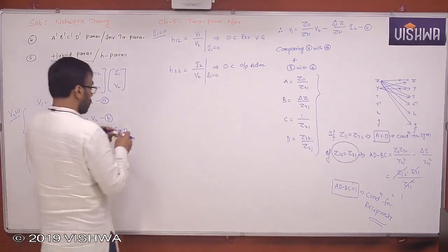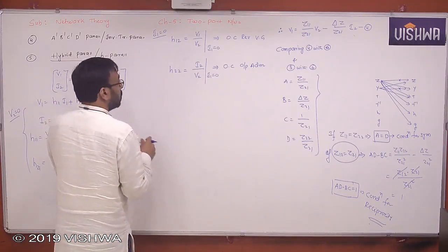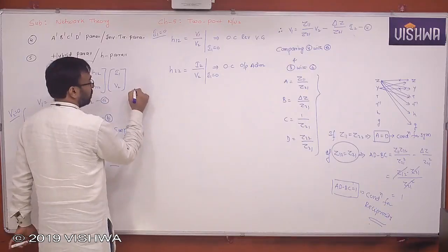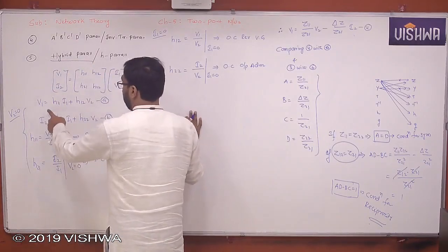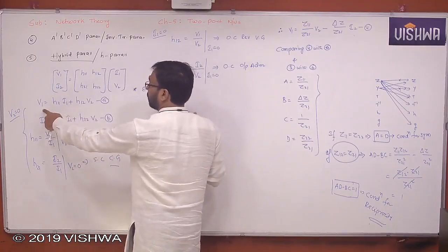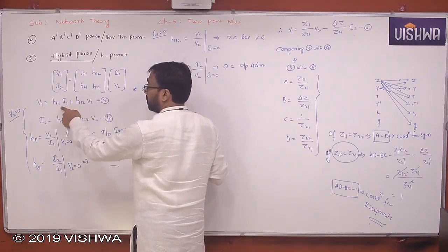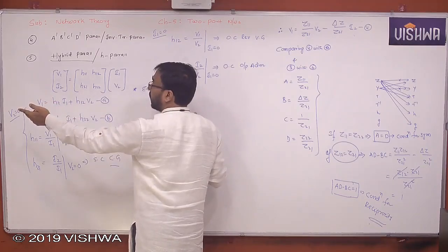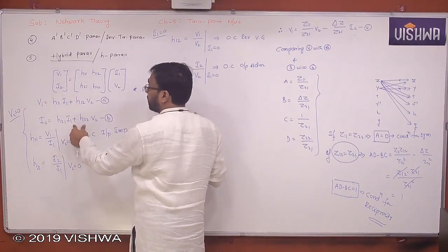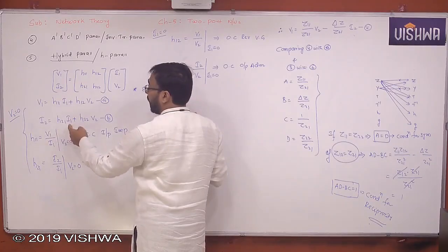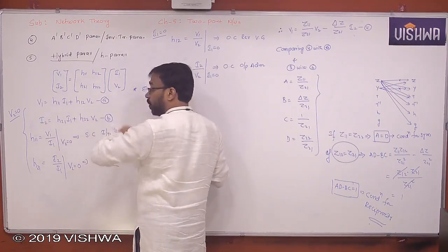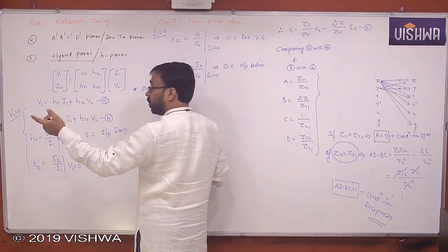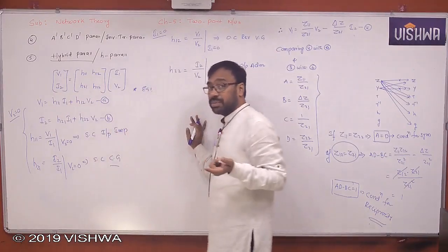Well, so the equivalent circuit, is it possible now? Yes, it is possible in this case because the first equation suggests that apply KVL or series combination on the input port side. The second equation suggests that go for parallel combination or KCL on the output port side. So one is an input port, the other is an output port side. It is quite possible.